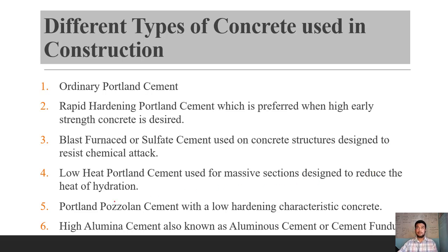So imagine pouring a very large amount of concrete, okay, for example, in the construction of large dams, it will really affect the temperature in the surroundings, which will be very difficult for you to work in. So they are using low heat Portland cement.